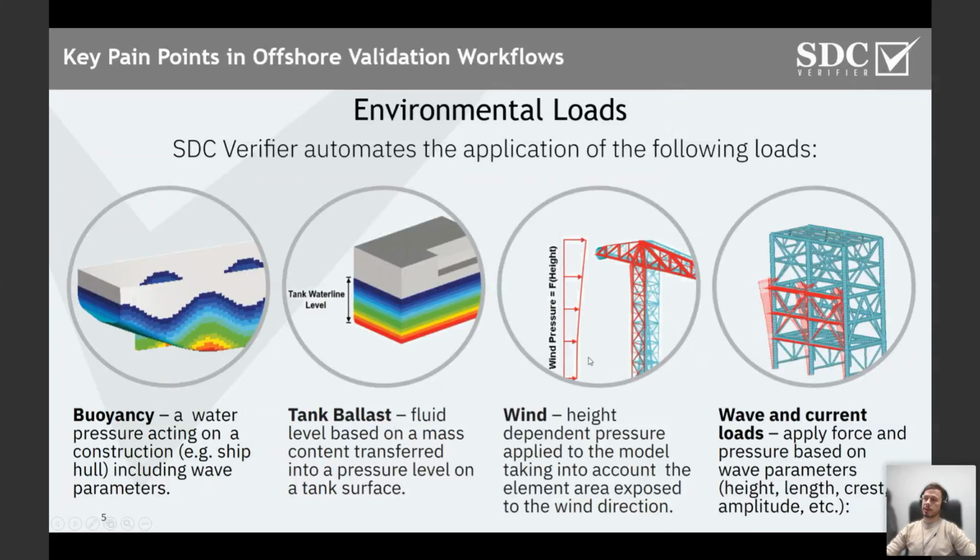Then one of the also most serious loads which acts on offshore structures and any kind of structure, I would say, is the wind load, where we should consider the exact value of wind load depending on the height, depending on the distance from the shore, and exposure, different directions, and so on.